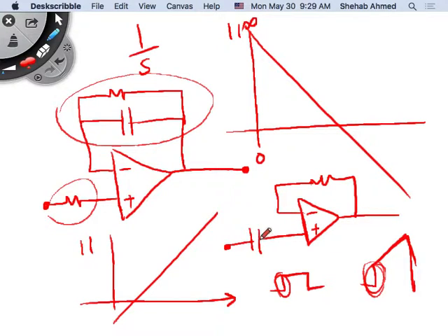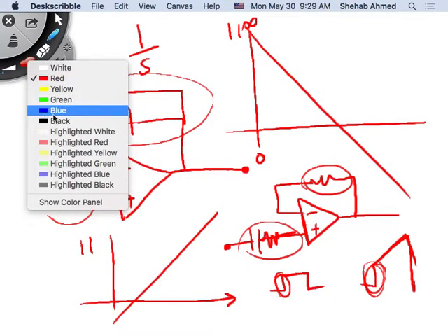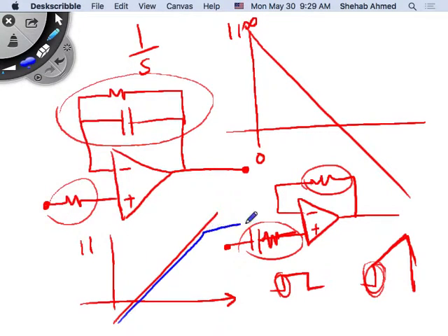We said that the solution to this is to put a resistor in series. How can you derive the new transfer function? Again, Z2 over Z1, right? And then it's a single time constant. Same single time constant, just the configuration is different, right? And then what did this do to the frequency domain plot, the transfer function magnitude plot? It changed it to something like this, right?